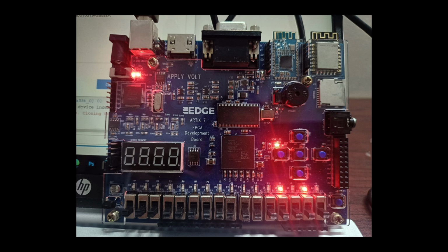Secondly, the 10 TMU cores run in parallel, processing all 10 neurons simultaneously every clock cycle. Thirdly, the entire inference for one image completes in just 160 clock cycles. This project demonstrates how neural network inference can be made hardware friendly and efficient, which is very relevant for edge AI applications where power and speed matter.